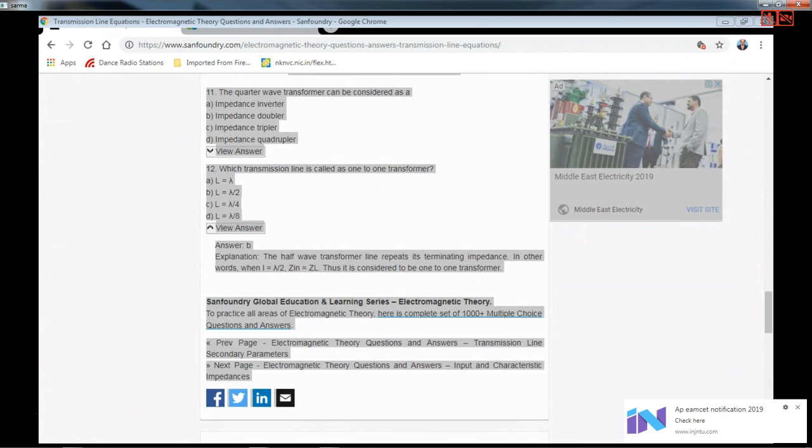Luckily, many of the transmission lines used at very high frequencies, VHF and UHF and further, can be considered almost like lossless lines. So at all these high frequencies, we can easily imagine that they are lossless lines, and thereby the S value can be measured at various locations by taking the ratio of maxima and minima at several locations. That's the advantage with your S value.